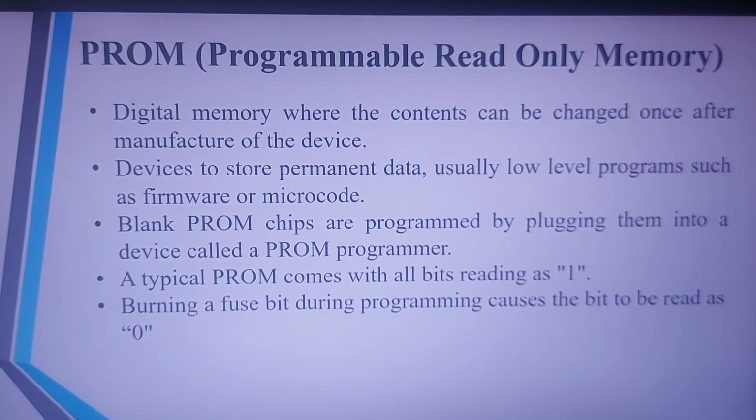This is a digital memory where the contents can be changed once after manufacture of the device. In the basic ROM, the data cannot be changed because it is hardwired, but the revised version, that is the PROM, gives the option to program it only once. So these devices are also called one-time programmable memories.